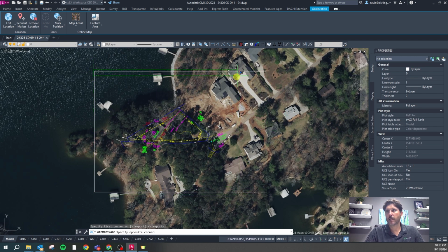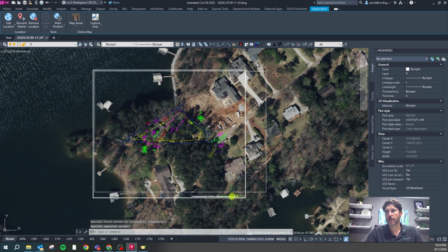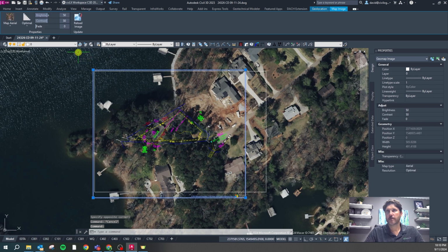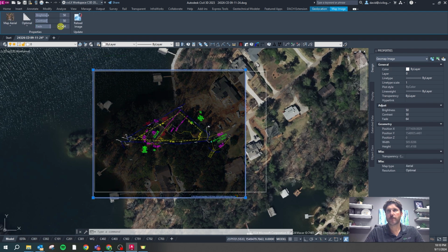And remember, we had a lot of information on this side of our screen and model space, so I don't need to go all the way out there. But I will go down a little bit below the rectangle because there's a logo that shows up in the aerial, that little Microsoft logo. And then you can grab it, fade it, maybe between 50 and 70%, depending on what you're doing for preliminary. Change this pixelation to very fine.